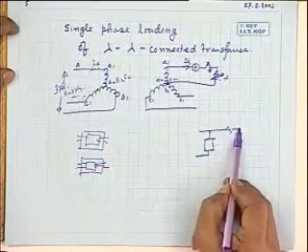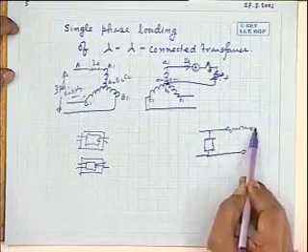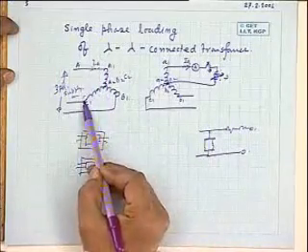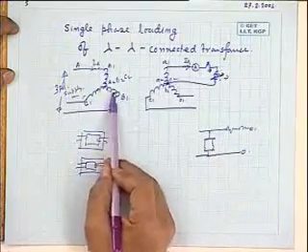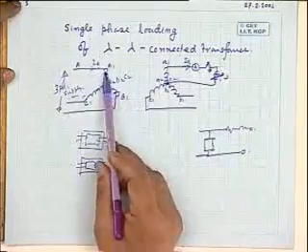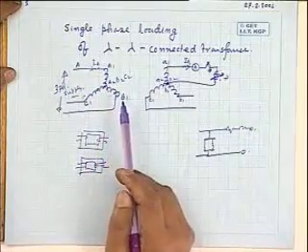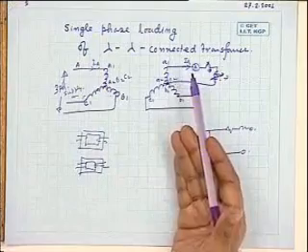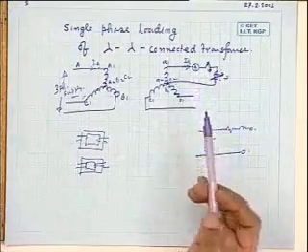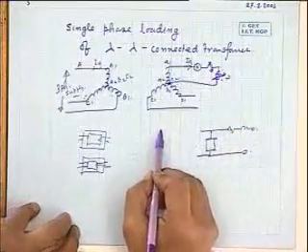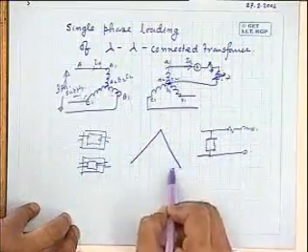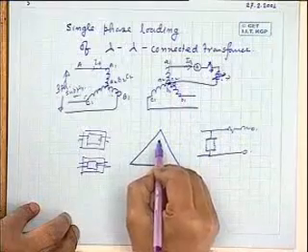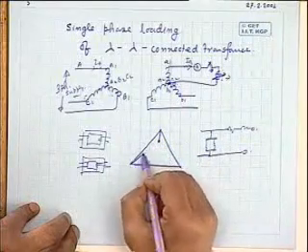In a transformer, what is the impedance? You draw like this, per phase. This is Rx. For the B and C phase transformers, nothing is connected here. So what is the equivalent circuit here? Only this branch between this point and this point, high impedance. Similarly, for this, a high impedance path is there. So what happens? Current really cannot flow through this high impedance. But then, who satisfies Ohm's law here on the secondary side? Voltage I have applied, there is some impedance. Actually, to satisfy this on the secondary side, it happens like this: this neutral point, this O point, as you go on loading, will come closer to here.